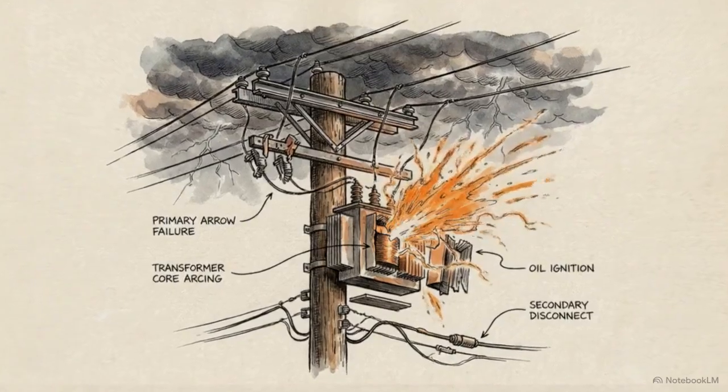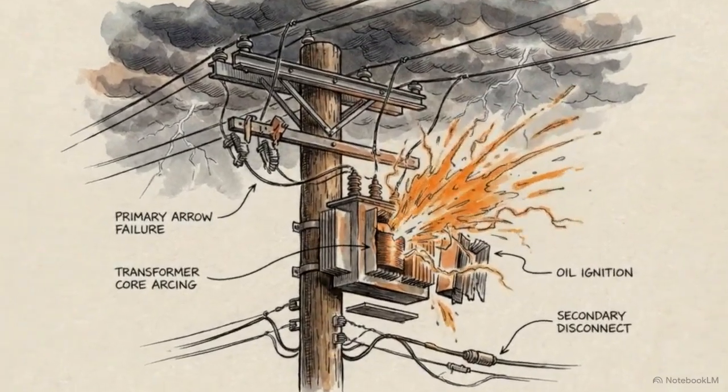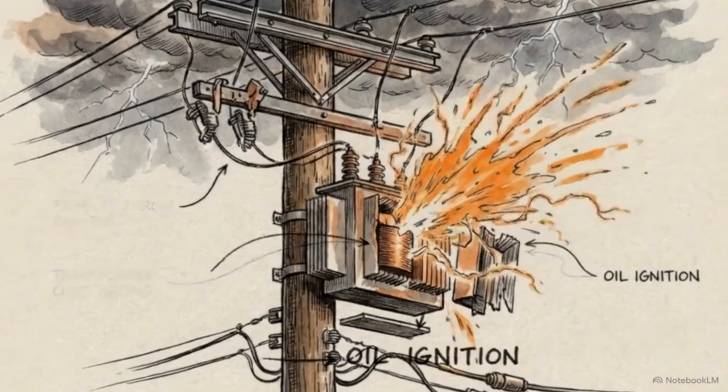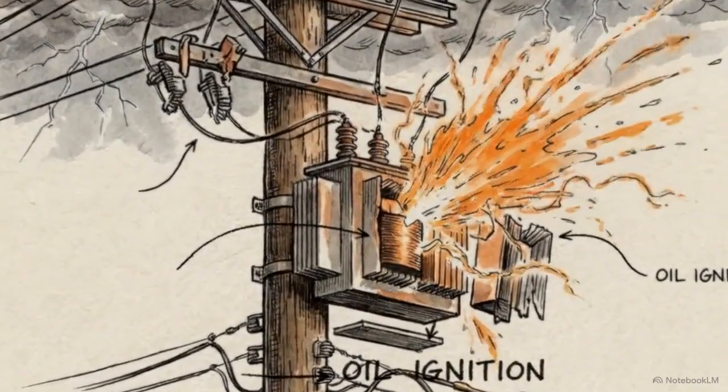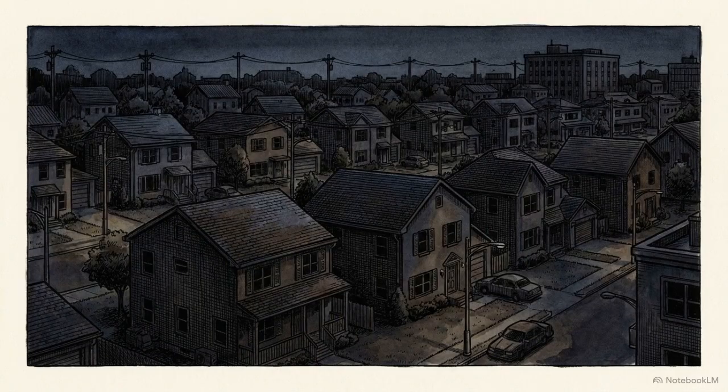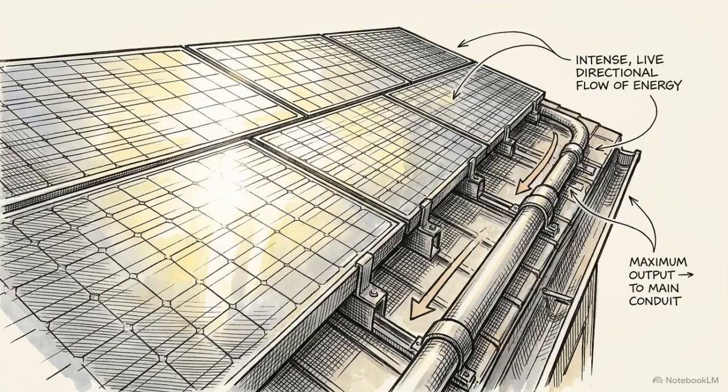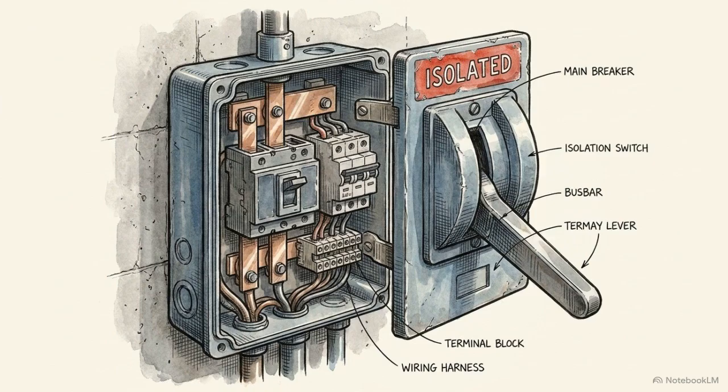Accurate accounting is important, but pushing private power backward into a shared municipal grid creates a severe, potentially fatal physical risk. Consider a localized blackout. If the neighborhood grid dies, your home's solar panels are still sitting in the sun, actively generating live electricity. To prevent disaster, solar systems are legally required to include a safety feature called anti-islanding protection.